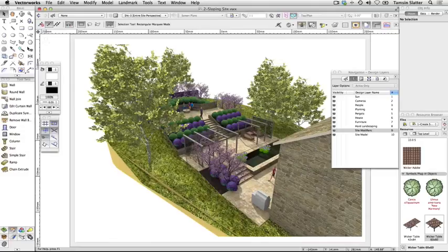Create a simple slope. A site model can be created from stakes or loci that represent individual height measurements. Alternatively, it can be created from 3D polygons that represent contours. In this exercise, you'll create a simple slope from stakes representing individual level measurements.